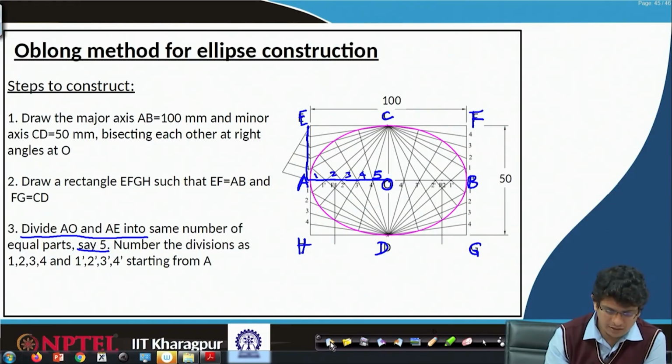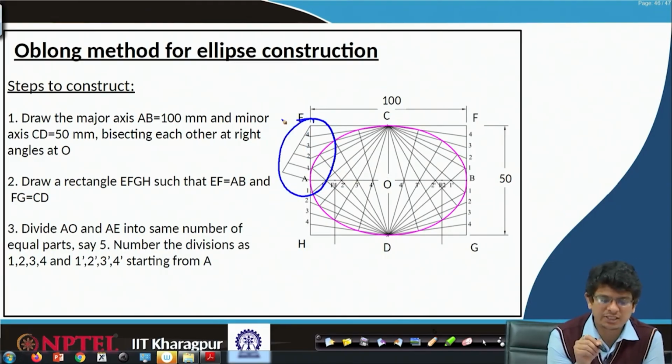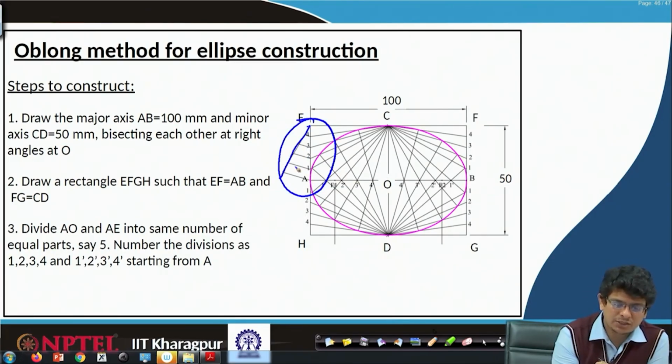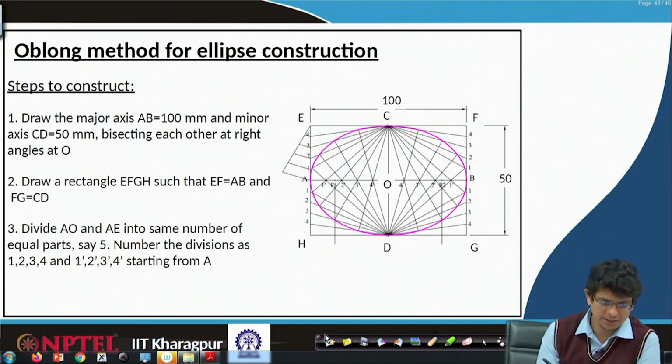For example, here, just for the class purpose, an inclined line is drawn, that is divided into arcs like we constructed last class, something like 5 arcs, 5 equal divisions. Then the last point has to be connected to the first point, then parallel to that one has to construct lines, so that we will have those inclined portions. That is the way one has to construct it. So, here we have divided into 5 equal parts and also 5 equal parts.